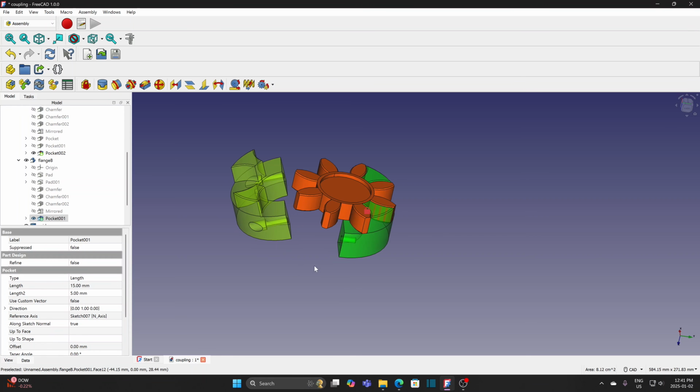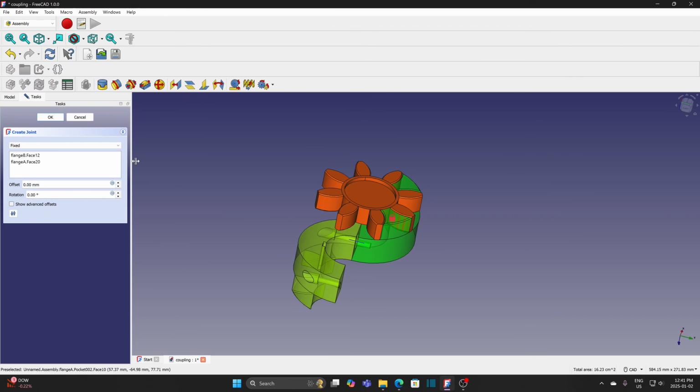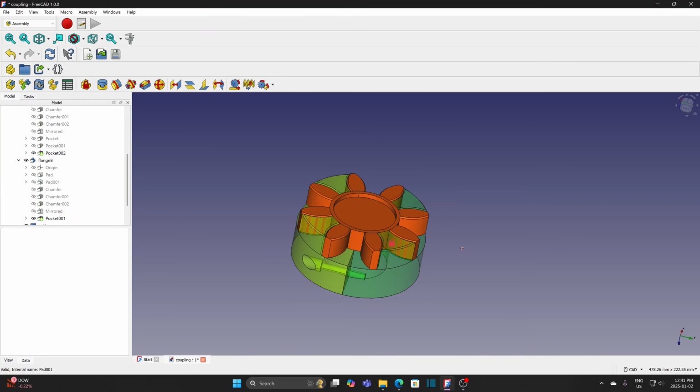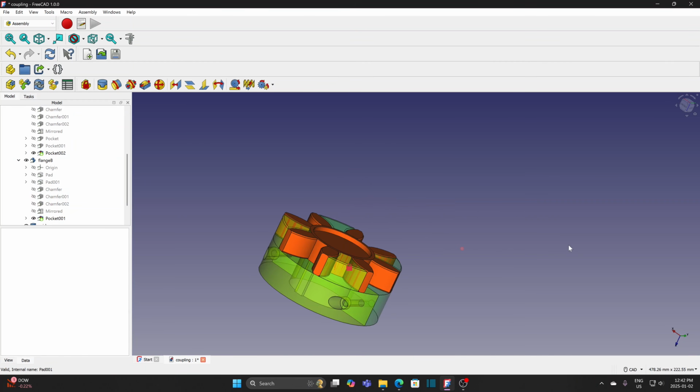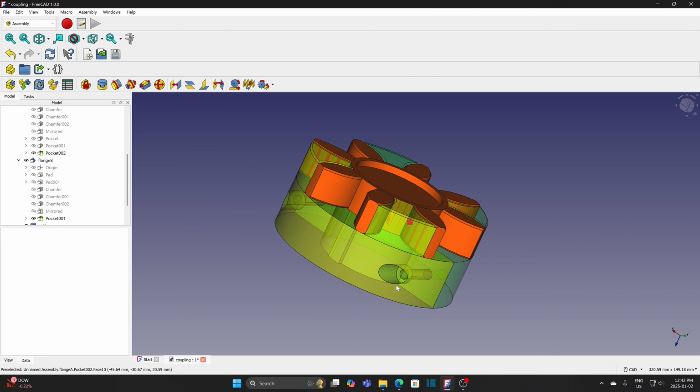Select the surface of both flanges. Create fixed joint. The assembly is smart enough to put them together and match two rectangles. Rotate it 180 degrees. I can bring the screws into the assembly but cannot insert it into the hole with the assembly. I have to insert the screw directly from the fastener workbench.